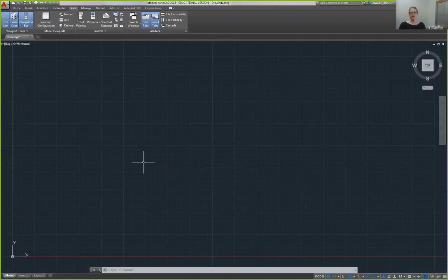In other words, if they were drawing a 100-foot line and they only had 20 inches of paper space, they had to figure out that they were going to have a scale factor of about 1 to 4, 1 to 5. In other words, 1 inch would actually be 5 feet, and that would be indicated somewhere on your paper.